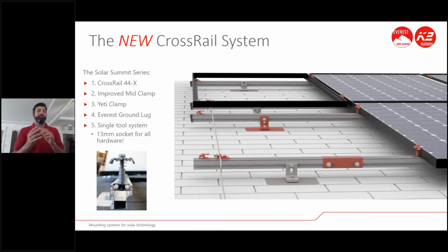CrossRail system, we're still carrying 48X, 48XL, and obviously 80. A 44 is that perfect in between that is lighter weight but still functions across the nation, still gets 4 foot, 6 foot spans, and we'll talk about that here in a minute. So we've been introducing the CrossRail 44X, which I'll show you in a second how the profiles look. They're slightly different. And then we've improved our mid clamp to have single tool features and a new little stem, so you have more wire management. And again, I'll show you that in the next couple slides.